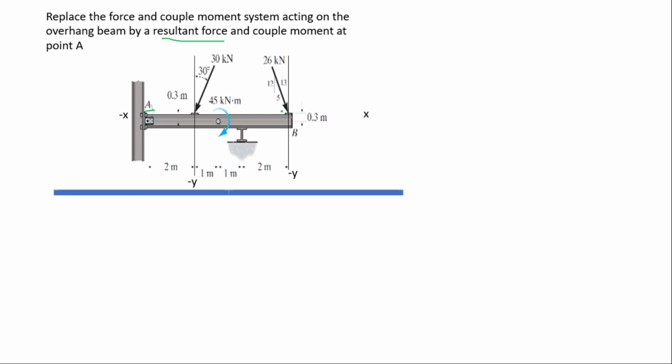Let's start. With this force, note that this force is coming to the point. Now note, when resolving forces, make sure the forces are away from the point. So we have a principle called the principle of transmissibility. That principle can help you transfer the force to another direction. Now let's handle this force.